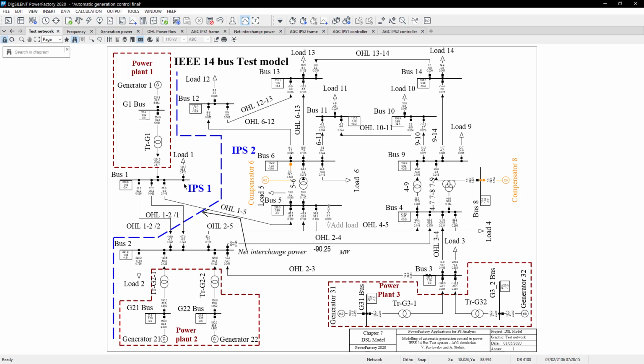Initially, we have power going from this generator here in this way. And then we have power going in this way, okay? But when we have the sudden disturbance, there is an increase in the load power here. And that is the reason that the active power transfer is reduced, okay? Because of course, this generator needs to cope with the new local power, okay?